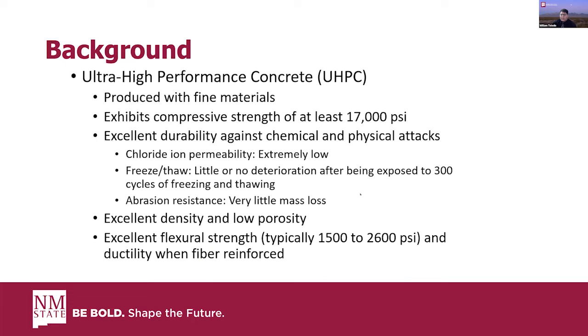Okay. So the overlay material used in this study is going to be an ultra high performance concrete or UHPC. UHPC is produced with fine materials, with the coarsest material being a fine sand passed through a number 4 sieve. UHPC exhibits compressive strengths of at least 17,000 psi and shows excellent durability against chemical and physical attacks. It has extremely low chloride ion permeability and shows little or no deterioration after being exposed to 300 cycles of freezing and thawing. When tested for abrasion resistance, it had very little mass loss, and has excellent density and low porosity, as well as excellent flexural strength, typically around 1500 to 2600 psi, and is ductile and fiber reinforced.